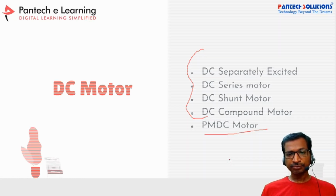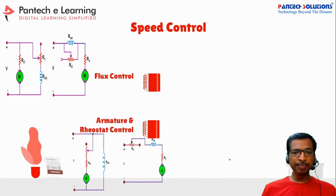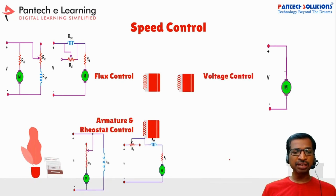And how we can implement the speed control mechanism. So there are three different types of speed control mechanism. One is called flux control. In the flux control, you have to keep the voltage constant on the armature side. In the field winding, you are going to vary the voltage by implementing a variable rheostat. So this is the variable rheostat, and whenever you are changing the field current, then the speed of the motor is going to vary, right?